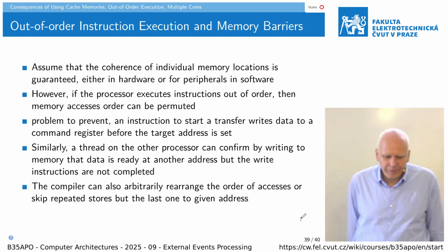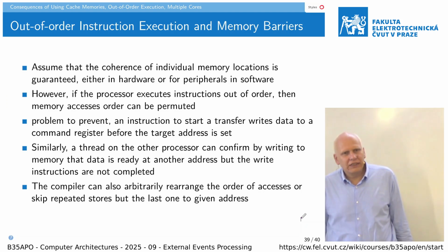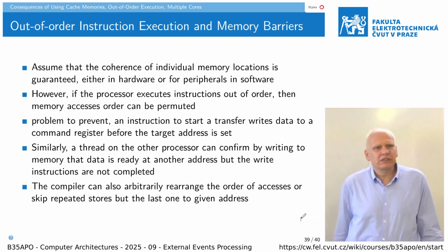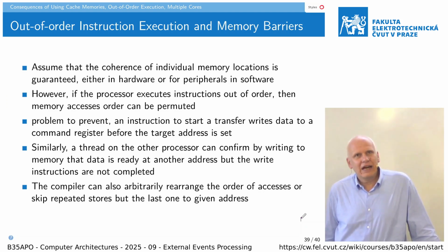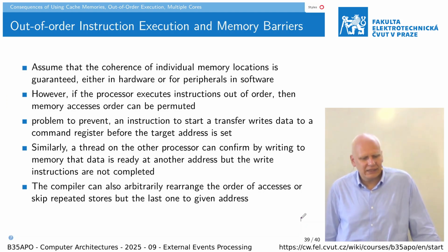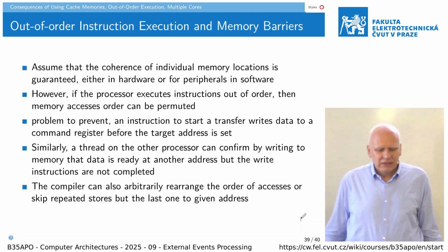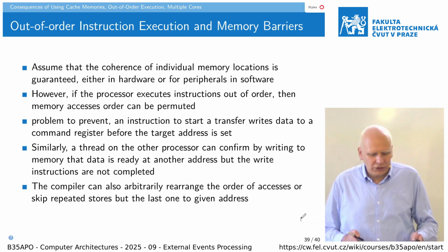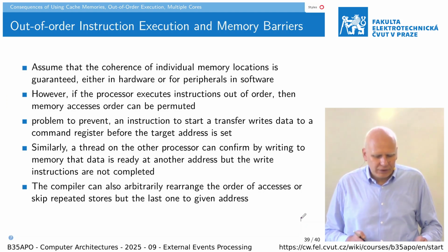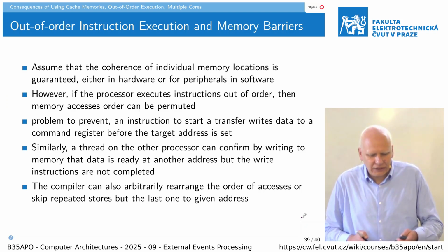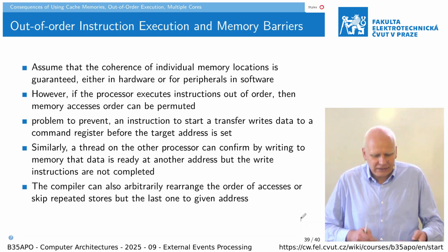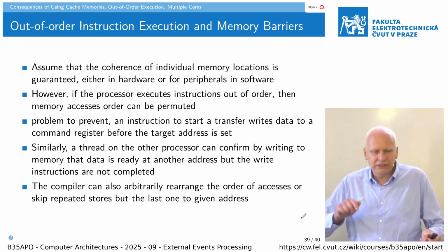So even though, to speed up the processing of instructions, there is this attempt to enhance the throughput, to execute instructions out of order, and so on, then it is necessary to find some sequential points and ensure by some barriers that, for example, now all the other instructions are finished, and this is your last instruction which starts the transfer.